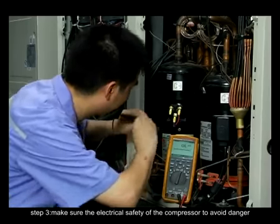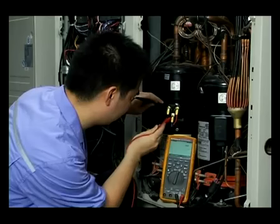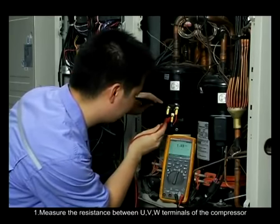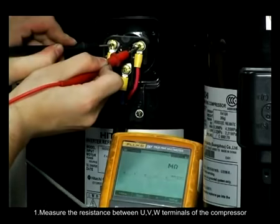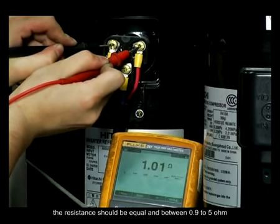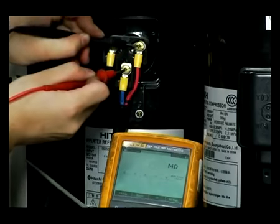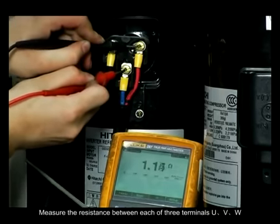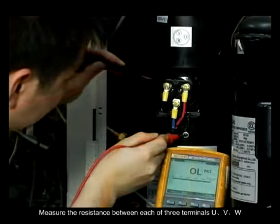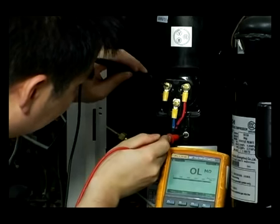Step 3. Make sure of the electric safety of the compressor to avoid danger. 1. Measure the resistance between the U, V, W terminals of the compressor. The resistance should be equal, between 0.9 and 5 ohm. Measure the resistance between each of the 3 terminals, U, V, W, and the ground to make sure it is in the mega ohm range.